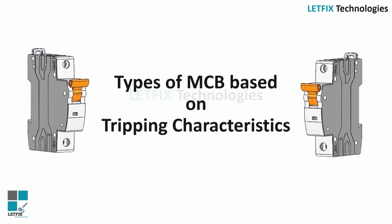Types of MCB based on tripping characteristics. MCBs are classified into different types according to tripping over the range of fault current. The important MCB types are Type B MCB, Type C MCB, Type D MCB, Type K MCB, Type Z MCB.